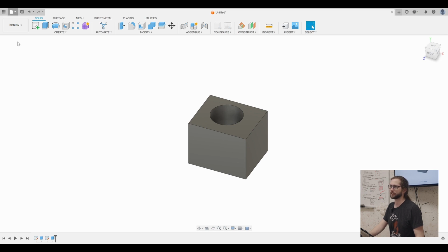And can you keep working on it as its own space, or can you import it into something else? You can also import it in as another body, and we can talk about that in the intermediate steps. We'll actually do that when we're talking about how I would grab a 3D model off the internet. So it doesn't give me the option to just save as. Right. The two things that you can do are save it to their cloud, or export a body as an STL.